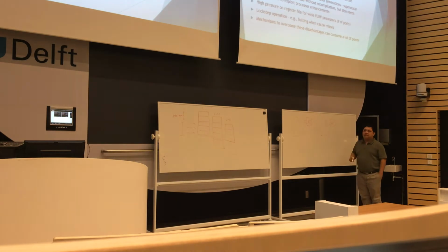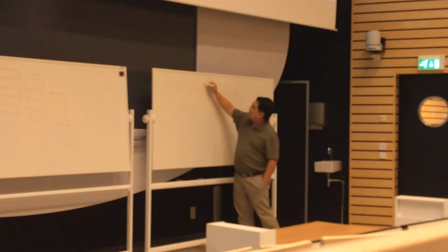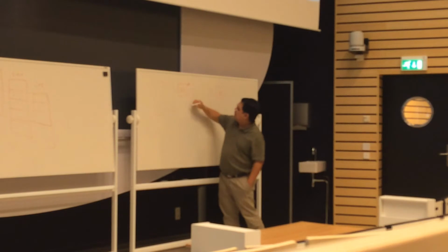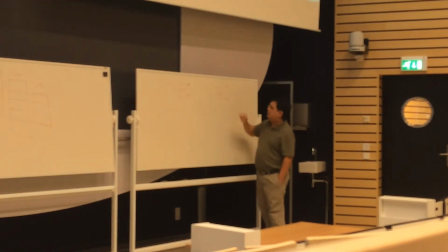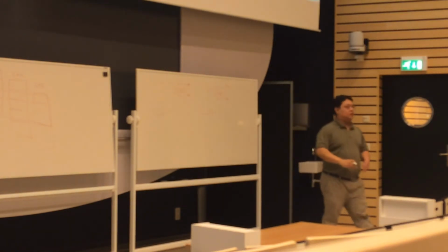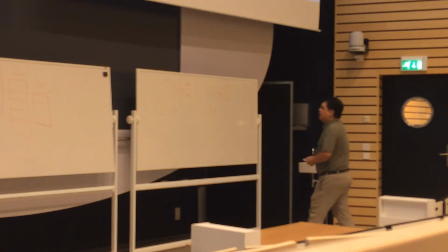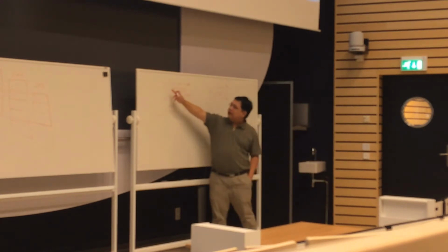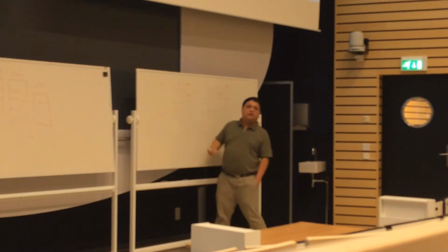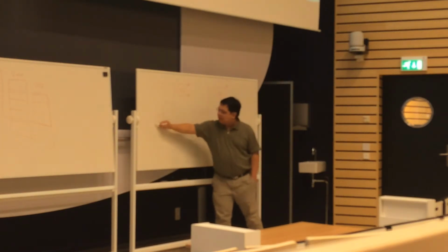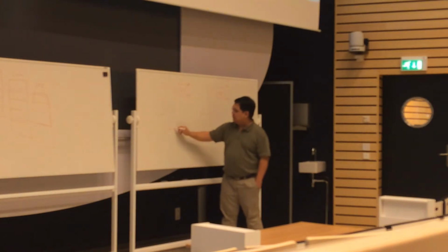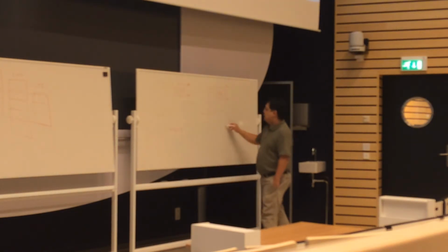But the problem is that I would like to access a register that is on, let's say, the lower half of my register file. Because now this is, for example, register 0 to register 31, and this is now register 32 to register 63. They used to be in a single register file, but now I cut it in half. By cutting it in half, I have a much reduced number of ports per register file. This part of my processor is called a cluster, so cluster 0, and this is then cluster 1.